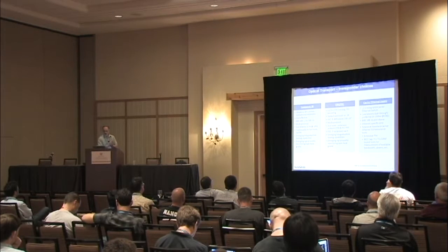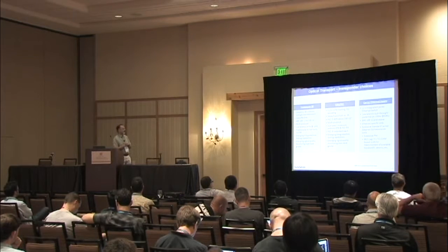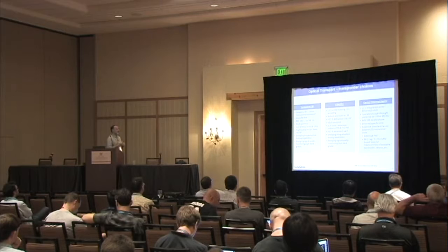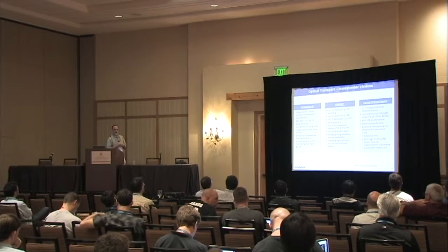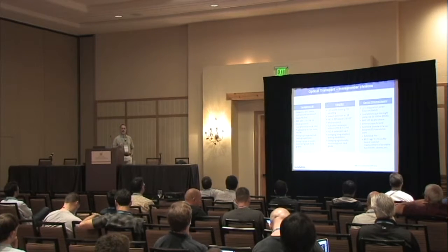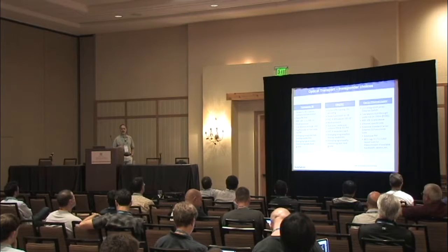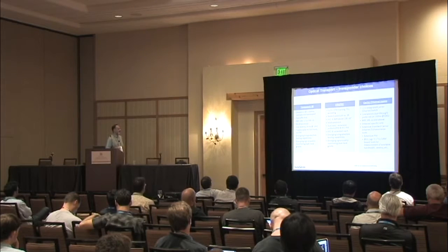Looking at transponder choices, and that's external transponders, not inside the switches. The simple transparent 3R, layer 1: retime, reshape, and retransmit. This is the most cost-effective option. Bit error rate within the standard industry ranges of 10^-12, 10^-14. Multi-protocol, 10 gig Ethernet, it's a must: LAN PHY and WAN PHY, but also Fibre Channel, all the rates of Fibre Channel, InfiniBand or SONET or SDH, it's interesting to have.